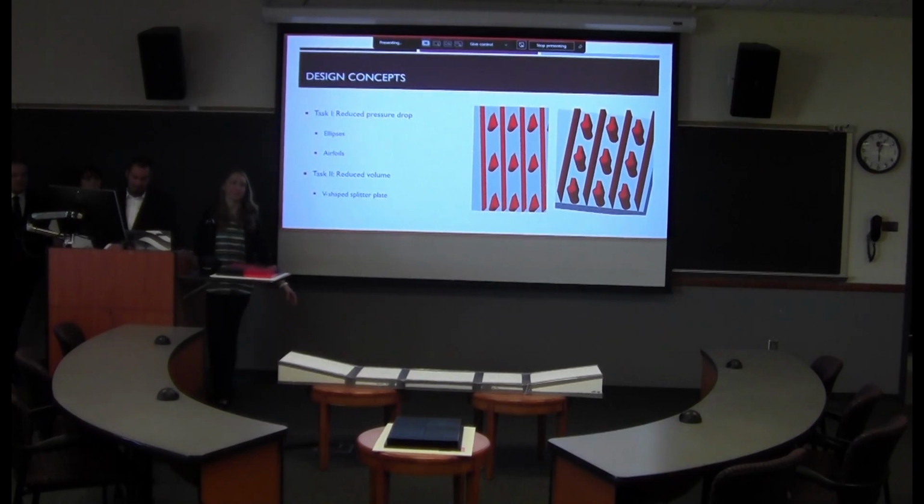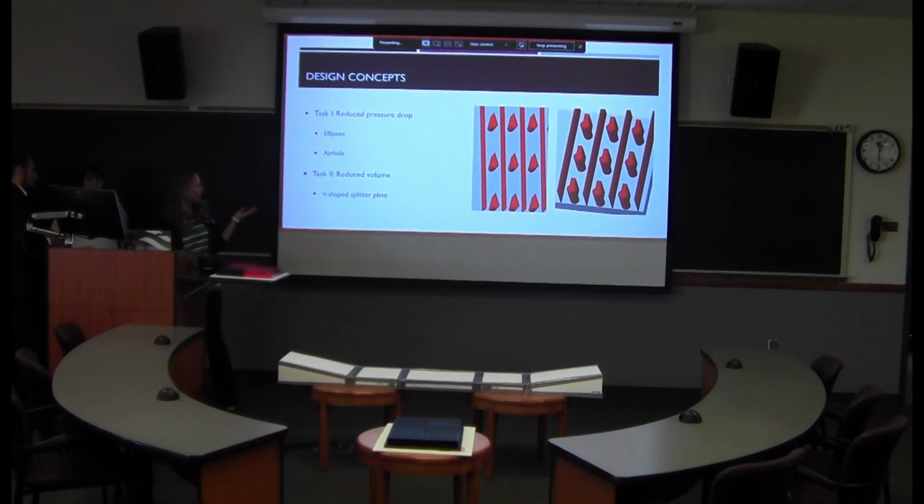Hi everybody, my name is Liz and I was part of the thermodynamic calculation subgroup. So last semester we came up with a bunch of different variations of designs for the different tasks. For the first design, we primarily focused on ellipses and airfoils this semester, and we have a couple of little models going around of a bunch of different variety. But those ellipses and airfoils we looked at, and in preliminary CFD calculations this semester, we discovered that airfoils were much better at reducing the pressure drop than the ellipse design. So we worked on those and we tweaked the design a little bit to see how we could accomplish improving upon that original design with an airfoil pin.